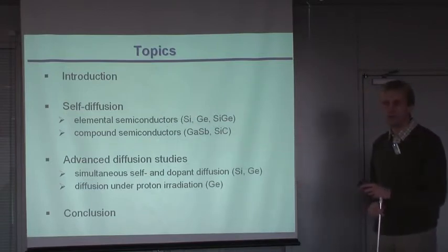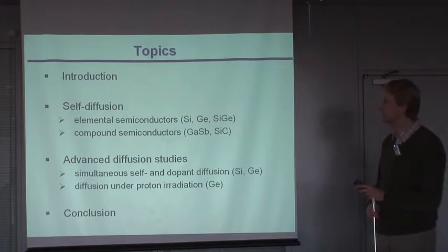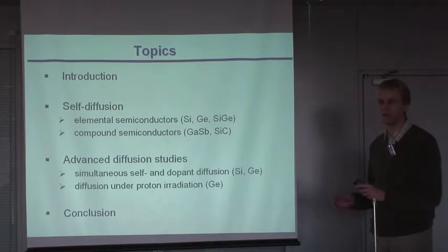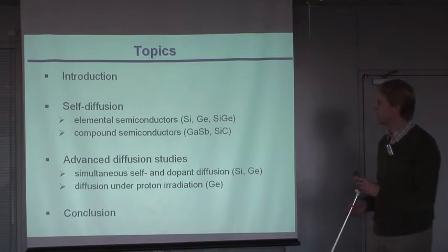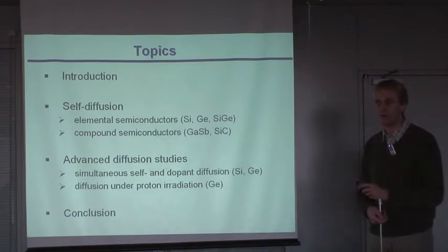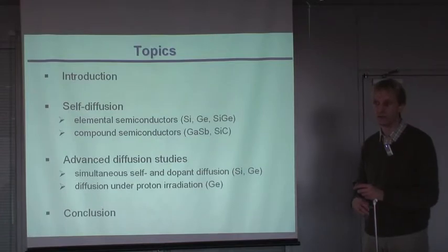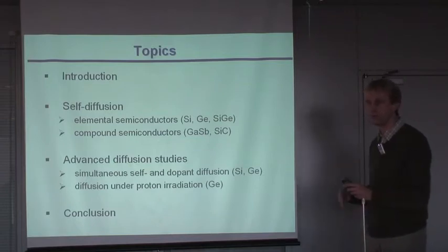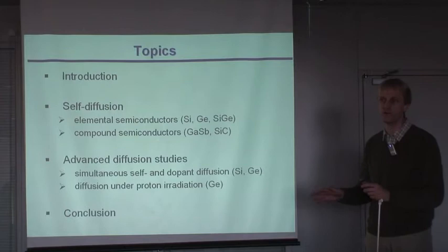tell you about some basic experiments on self-diffusion. Self-diffusion is the most fundamental mass transport process in materials. If you know nothing about a material, the first thing you should look at is the behavior of the diffusion of the self atoms in the material. That gives you a first indication of what the dynamics in the material are, and how much energy you need to move an atom from one lattice site to another. This is a baseline also for dopant diffusion and for all the other foreign elements.